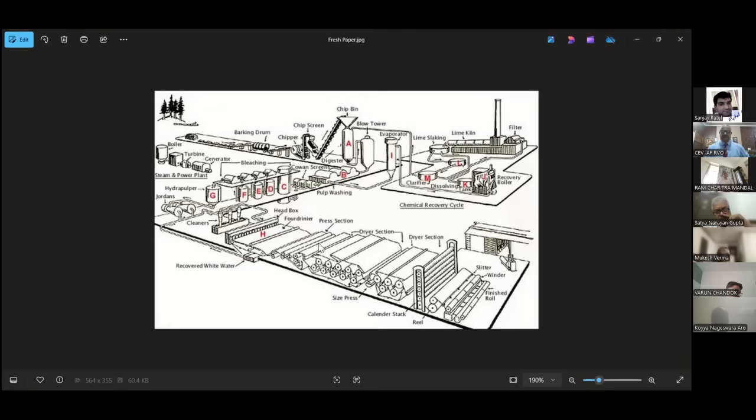Okay. So in the press sections, the initial press sections may have some blanket type rollers. So they press the paper pulp. So whatever extra moisture or water content is there is removed. Okay. And some are also heated, so it makes the process of evaporation faster. Okay. So after the press process, this goes to the dryer sections. Simply, in the paper dryer section it dries completely and comes into paper form.